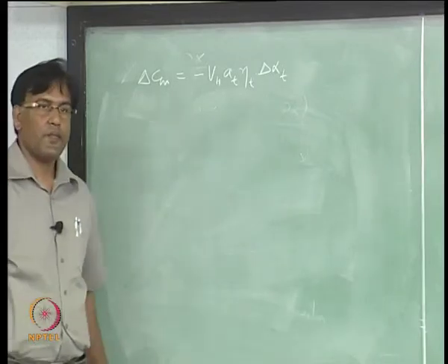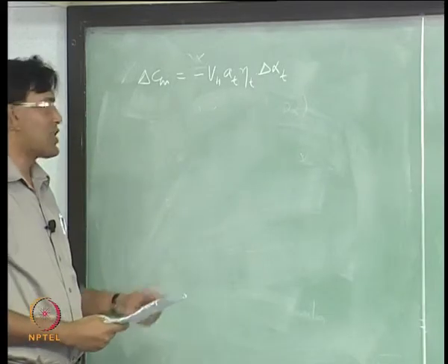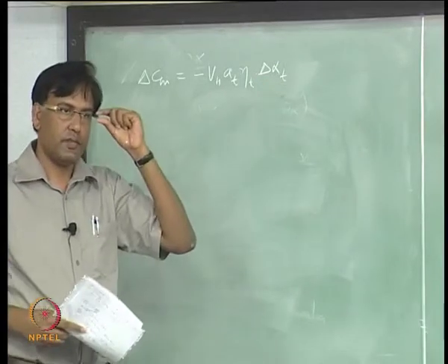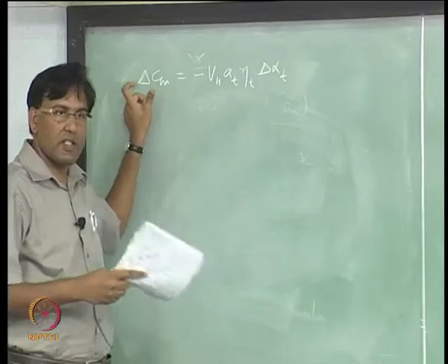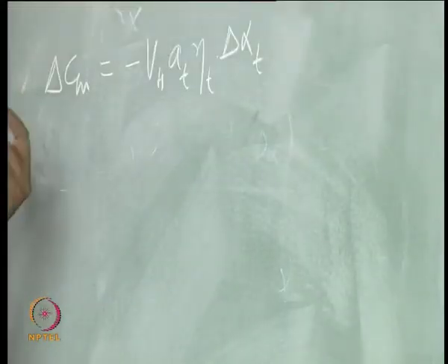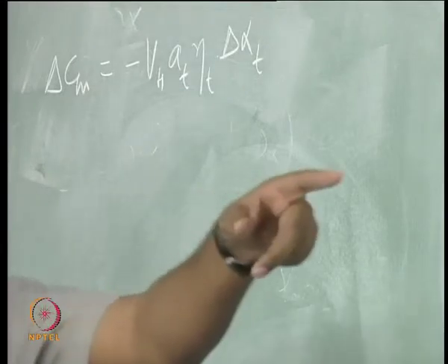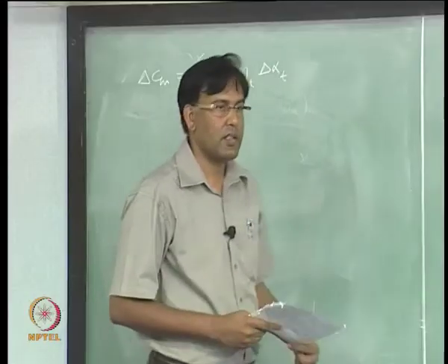Right. So, I am including this angle, which this expression we have written already, expression for CM. Now, I am writing down the expression for change in this CM because of change in angle of attack at the tail due to the pitch rate, right.